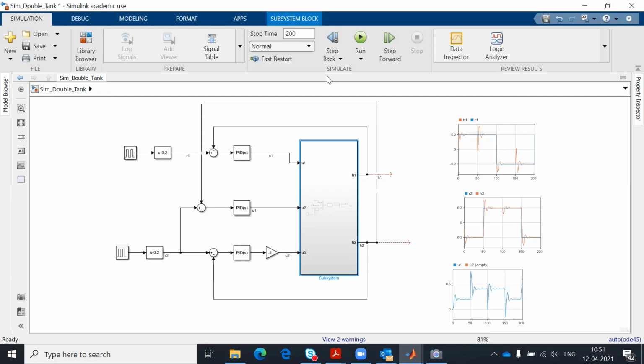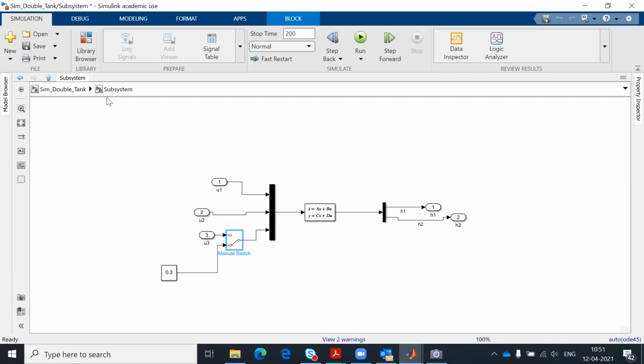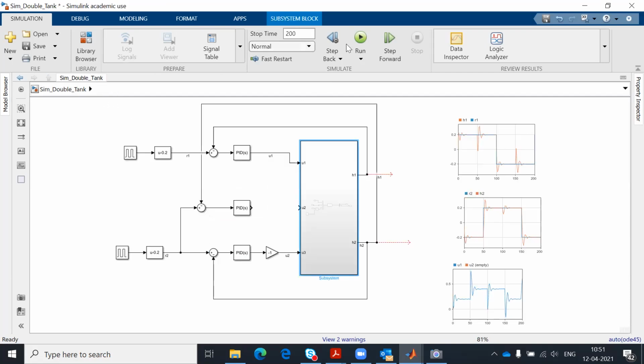But adaptive control is different from fault tolerant control, because in fault tolerant control, it's not a matter of changing the parameters. Let's say this is the controller we have designed. Now a fault happens, which means that you have switched the third valve off, it is not working. It doesn't matter how much you change the parameters of the controller. You will not be able to control the system because a sensor is gone or an actuator is out of order. Okay? You need to reconfigure the controller.